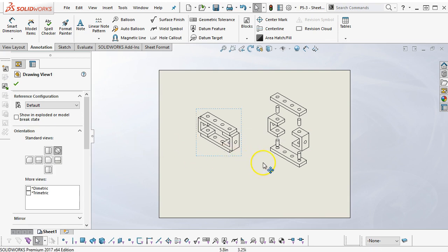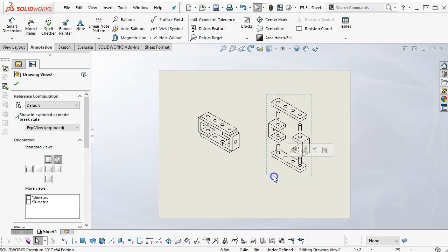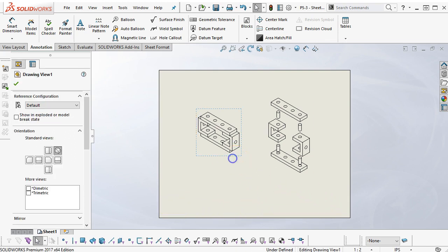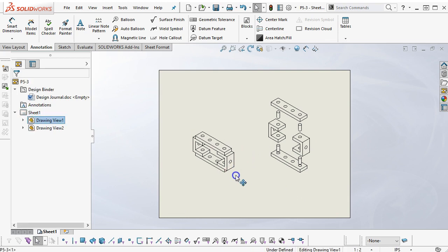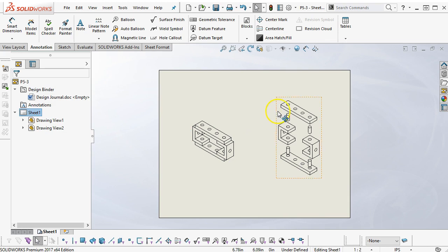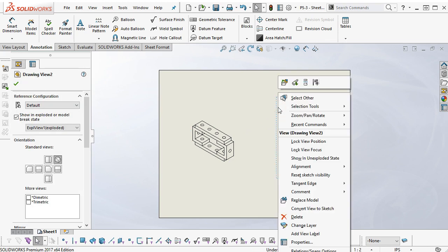So at this point, for expediency, I'm foregoing the title block. If you like the standard A size title block, it does take up about a quarter of the page. I usually modify the sheet to where it's just the important information across the bottom. So we'll save that for last. All right, so we have our items. We're not so concerned with the size maybe on this one. I do want to generate a bill of materials.